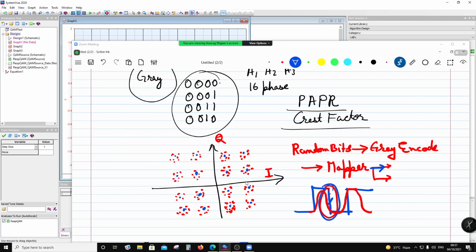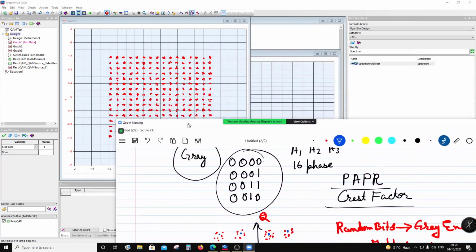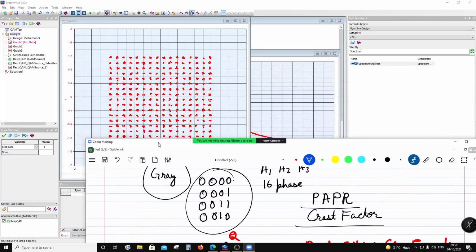This is because of the filtering here, the excess bandwidth, the roll off, the pulse equalization. So all these things contribute, the nature of the window, all this causes this to not be exactly these blue dots. They are going to be rather red dots, and in this constellation none of the effects of non-linearity or any other effects like noise are included. So right now you are looking at a pure source with a certain filtering, right?